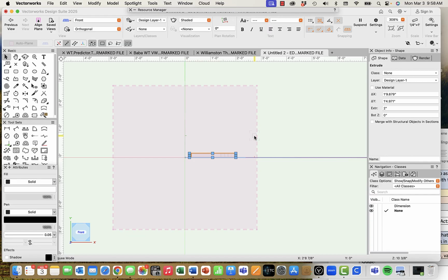So this is one situation where we have to let go of our 18-inch rule, and that is the height of the rise plus run equals 18 inches. Because as we're spiraling around and walking up this staircase, we have to have enough headroom above us that we're not smacking our head on the stairs. So I'm going to go ahead and move this up 10 inches, which is going to give us a total rise of 12 inches.